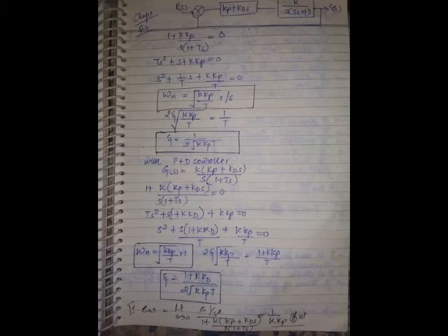So can we say that this controller is capable of improving the steady state response of the system? No, because error it cannot remove. On the contrary, it is keeping some error in the system. So we say that this controller is capable of improving only transient state, speed of response, provided whatever error it is keeping in the system should be acceptable in that application. Then only you can use this controller. Definitely some error it is going to keep.